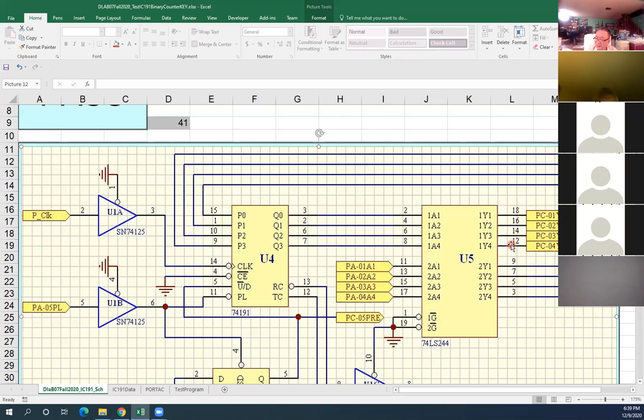The only thing is, something is wrong with pin 12 if you already replaced U5 and it's still the same. That means something is wrong with that output. But that is normally the way of troubleshooting. You get a wrong output, if you get a right input, then that's it.